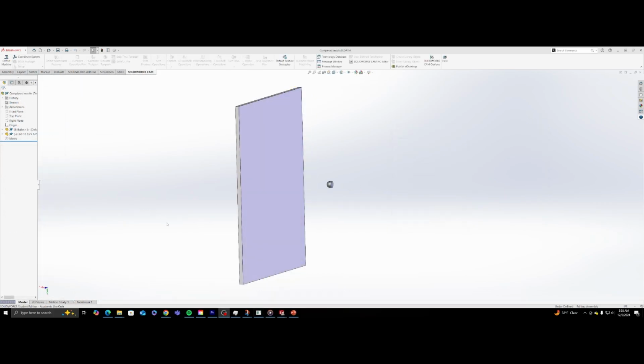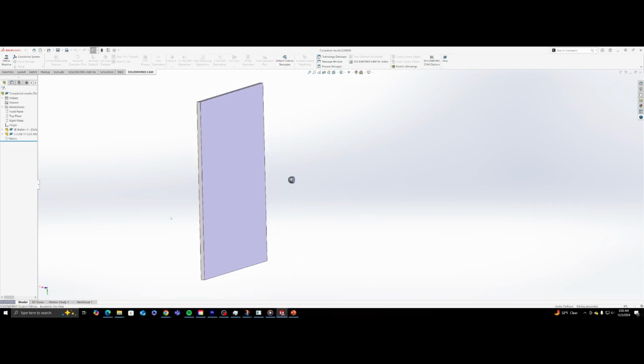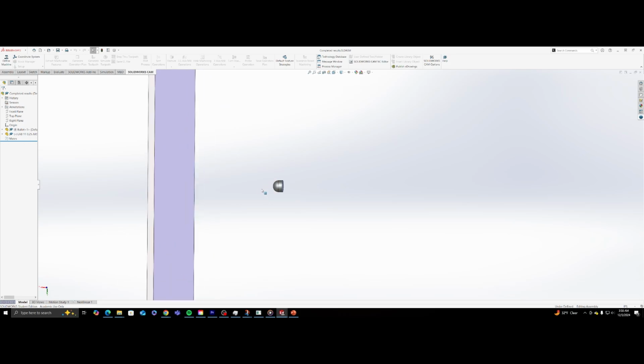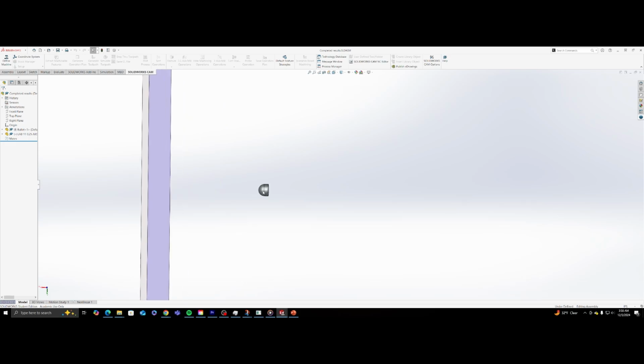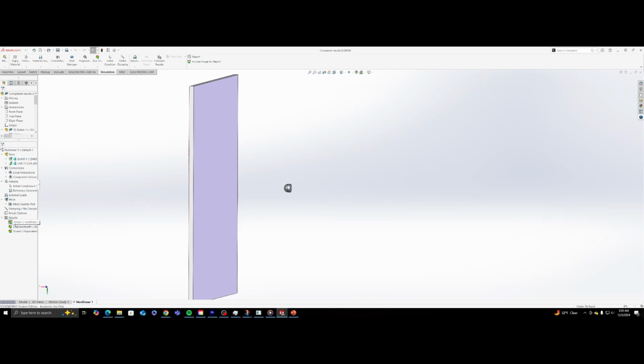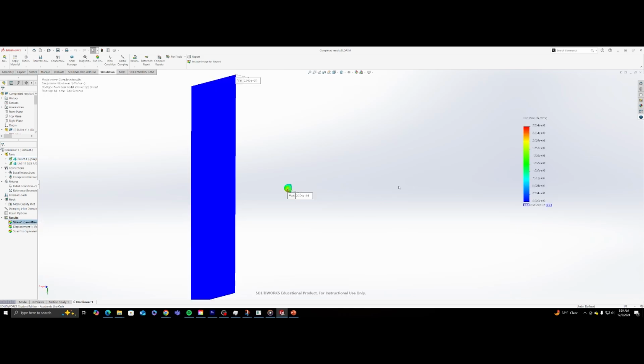Alright, now that brings us into some of the limitations that we had using Solidworks in this study at large. Anytime that you try and transfer over data, or you try and run it, or in this case of the bullet, since we initially tried 5,000 meters per second, the bullet obviously fell into 1,000 pieces, destroying this mesh. And so we would always get an error that said mesh broke, cannot analyze, and it would fail. And of course it would do this at the 3.5–4 hour mark.